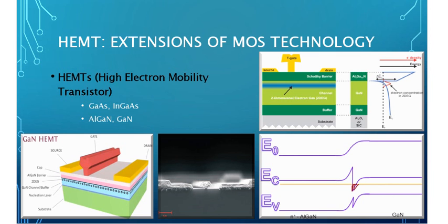As you can see here, I've displayed a couple of ways to show what a gallium nitride HEMT would look like. You have a gate; it's a bit different structure. It has a T-shaped gate. You have a source and drain, just like a regular MOSFET. But in this, you have a bit of a different technology, because instead of one material, you have different materials placed over each other, normally using molecular beam epitaxy. And they form what are called Schottky barriers. And then that mixed with your channel produces what's known as a heterojunction, which we see here